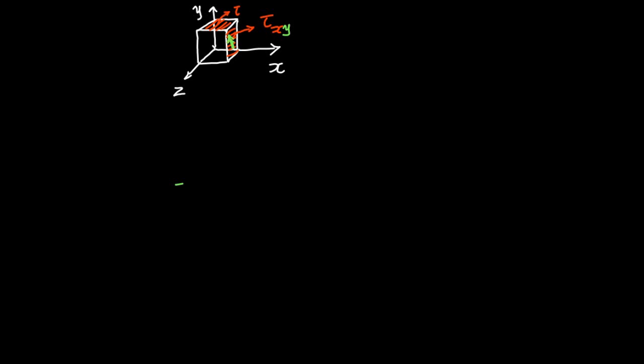Okay, similarly you can define the shear stress on this plane, in which case the shear stress is tau, and it is taking place on a plane that is perpendicular to y-axis. And let us say that you are bothered about the shear along the x direction, so you can write tau yx. Similarly, I can write for all the shear stresses, but you know, because of complementary shear stresses, tau xy is equal to tau yx, so I don't have to write two separate equations for them.